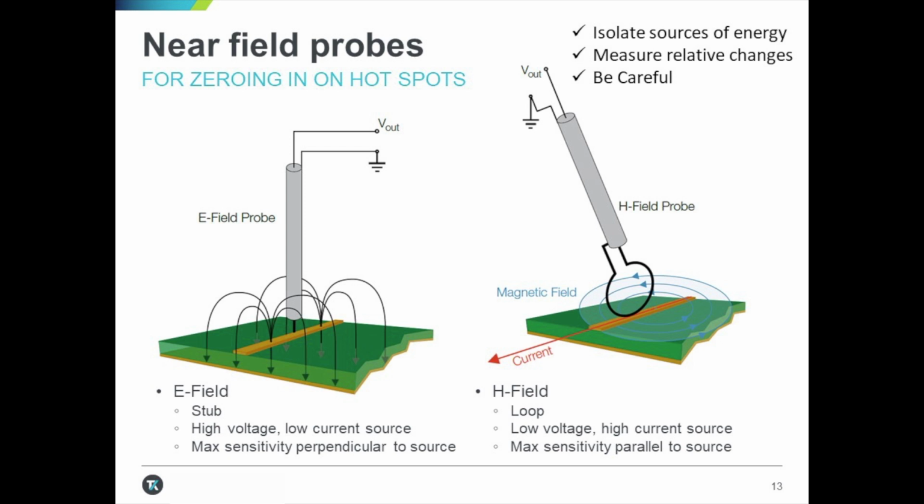In general, near-field probes are not really calibrated. From a diagnostics perspective, though, that is not much of a problem. From a diagnostics perspective, what we are really looking for is how much change, or relative change, we make to our signal. If we have a spot frequency that we know is a problem, and we have tried to mitigate that in some way with some shielding or a change in design, we can measure before and afterwards to find out how much we have affected the change.